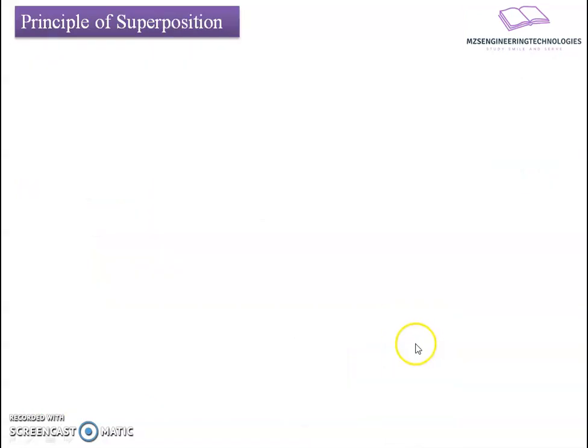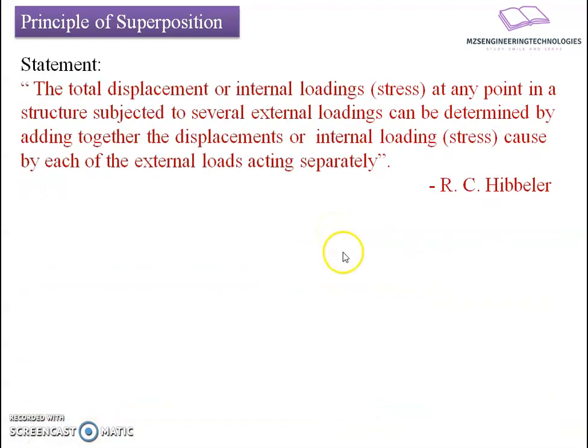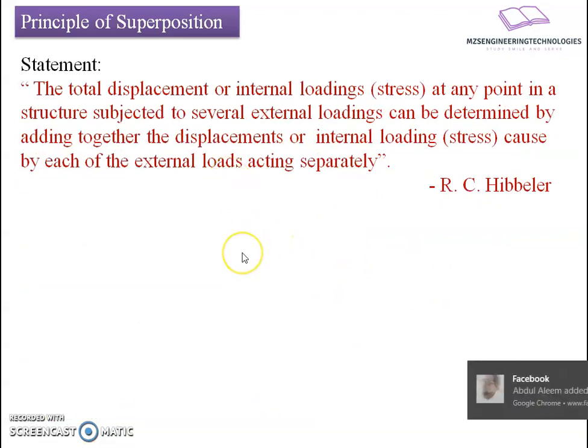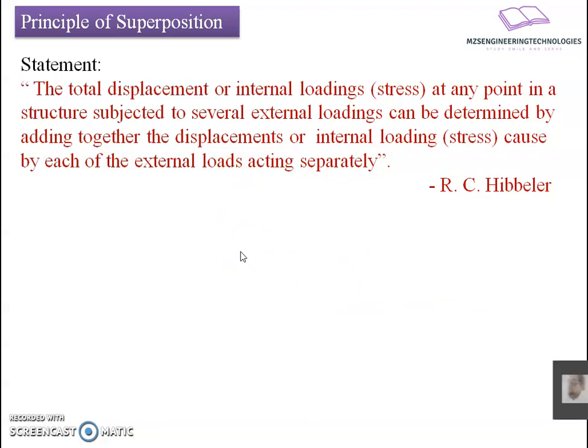Okay. Now we'll go towards the basic principle, which is said to be a pioneer principle for the analysis of determinate structures: the principle of superposition. What does this principle state? The total displacement or internal loading, that is stresses, at any point in a structure subjected to several external loadings can be determined by adding together the displacements or internal loadings caused by each of the external loads acting separately.